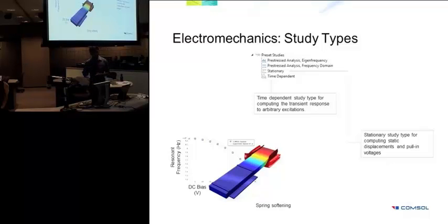So if you keep increasing the voltage, the resonator will keep deforming until a critical voltage is reached, at which it becomes very unstable and it snaps, or there is buckling or impact type of contact. Transient or time-dependent analysis can be used to calculate the transient response of such a resonator with increasing voltage, for example.